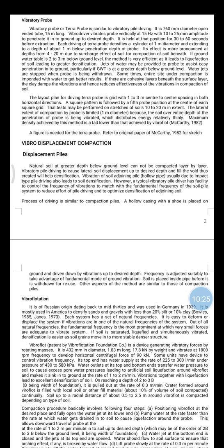Other aspects of this method will be similar to compaction. You have already studied compaction, and this is the same. Here we drive the hollow pipe with vibration. This vibration helps displacement of the soil, and displacement also helps densification. Due to the vibration, the surrounding soil particles are rearranged and densification of the soil takes place. So that is regarding vibro displacement, that is displacement piles.